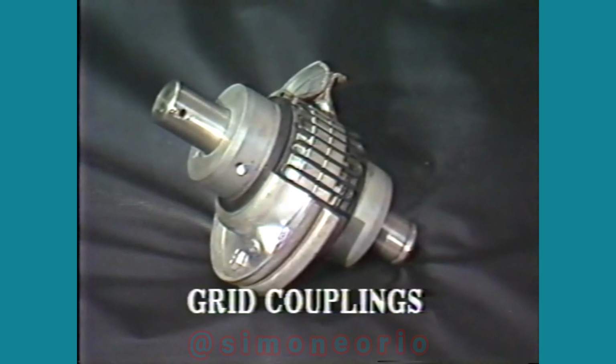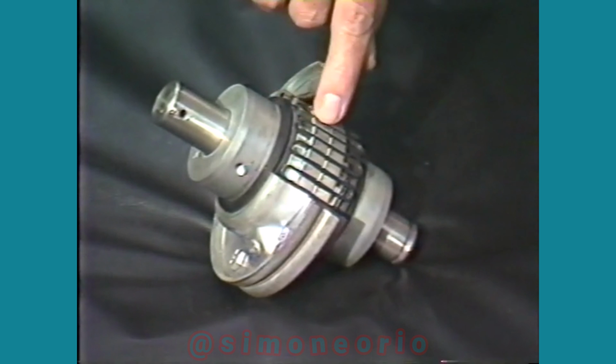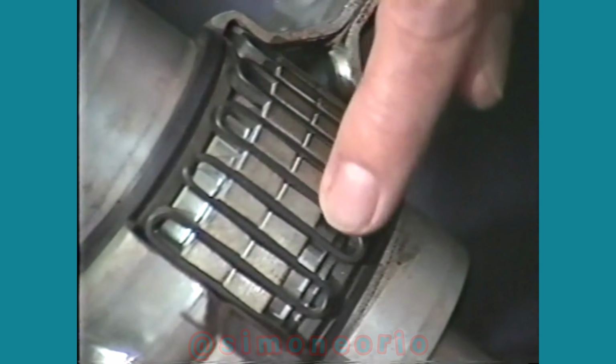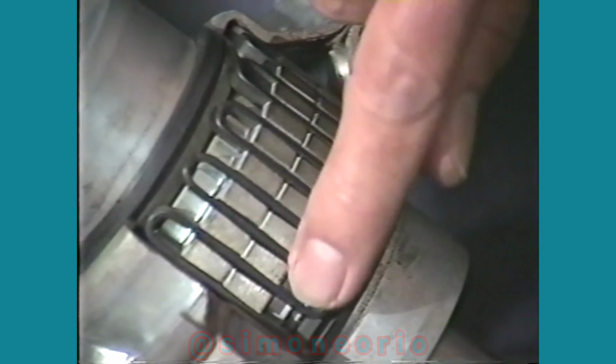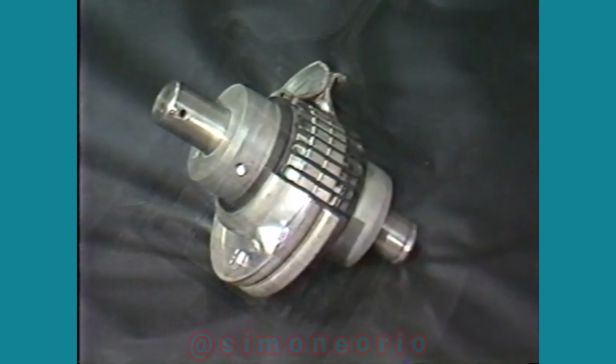Grid couplings. These hubs are machined to accept this center member called a grid. The grid flexes between the hubs and allows the hubs to be out of alignment. The grid also dampens vibration passing from one shaft to the other. A cover and lubricant must be used.